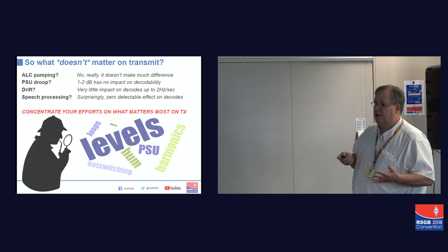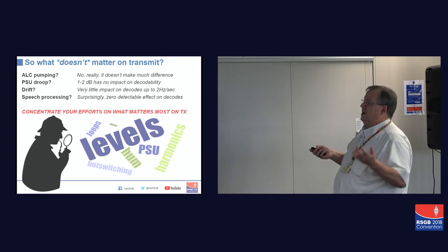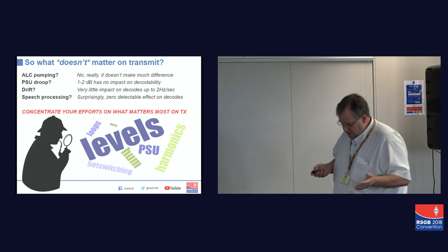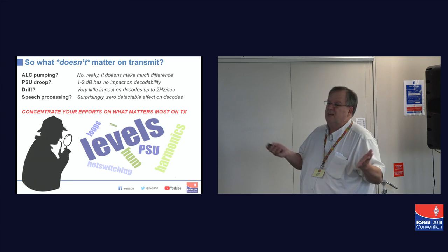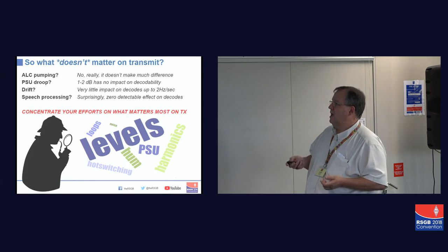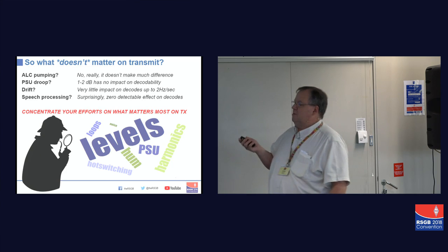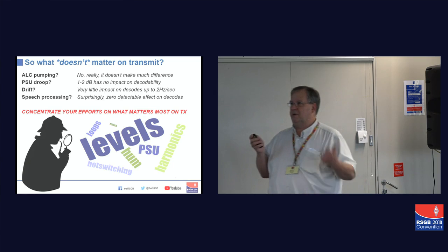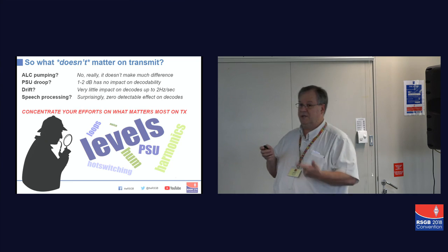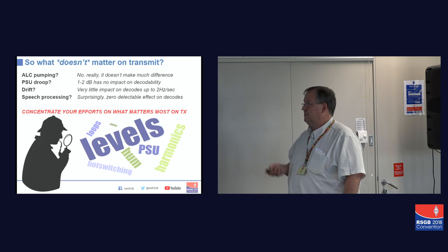If the power supply droops because it's not got big enough storage capacitors, it doesn't matter. A bit of drift, say around 2 hertz per second, doesn't really matter, it'll still decode. And weirdly, if you slam it through a speech processor, you would think that would cause all sorts of problems. I could not see any detectable change on my ancient TS440 or my new SDR. Absolutely no impact from speech processing, which is a bit counterintuitive.